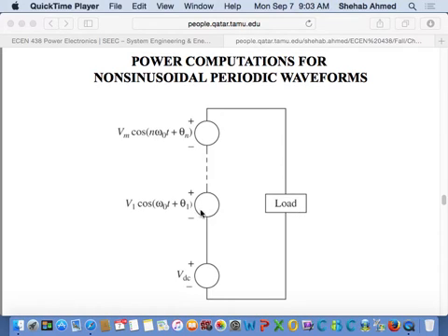This voltage superposition, right? If you have many of these sources and you have a resistive load, you would do superposition, correct? Take all of them out, use one, then add them up, and then figure out the final value of current. This final value of current is the sum of the contribution of these individual power supplies feeding that load, right? So you can find its RMS value by the identity that we talked about at the beginning. If you know that this is V1 cosine some angle, then the RMS value is V1 over square root of 2.